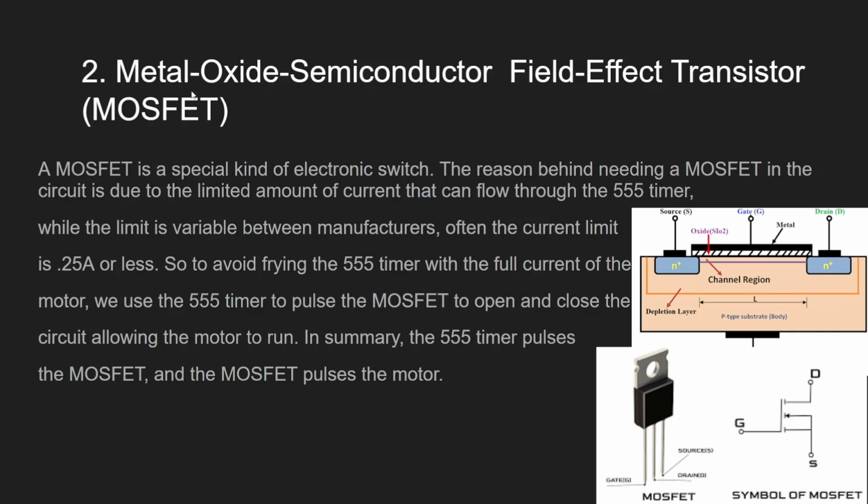The reason it's called a metal oxide semiconductor field effect transistor is that the name goes from the top down. If we look at the very top layer of this drawing of a MOSFET, there is metal. Metal is conductive, and the metal is connected to the gate pin. As you can see, there are 3 pins here. The furthest left is gate, then drain, and then source.